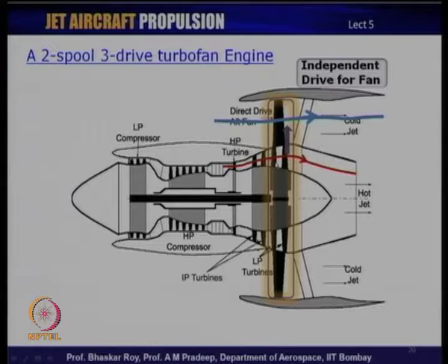This third set of turbines over here actually has a big fan mounted right on top of it, or right around it circumferentially. So, it directly sends power from the inner turbine blades to the outer big fan blades, which actually activates a very large amount of cold air mass flow and produces the large bypass flow.